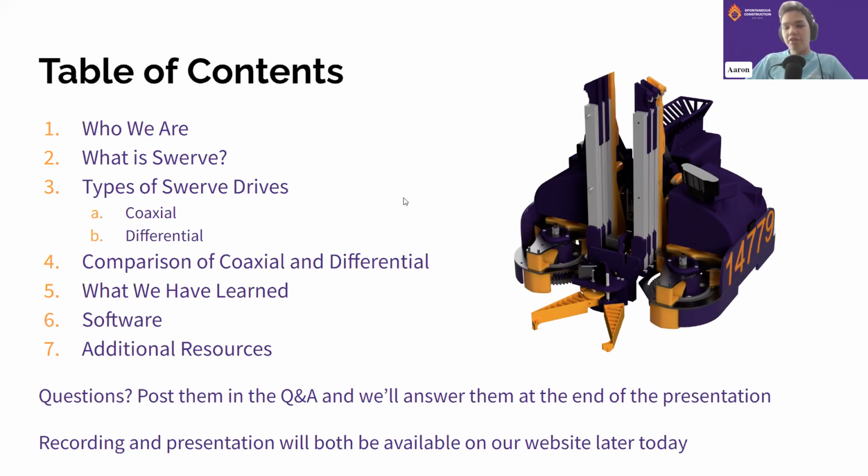This has worked fairly well for us, but I would recommend looking into other options for acceleration curves, because the moving average filter works, but it isn't perfect. There are some limitations, like you can't use it in the first few updates in a match, and using it for auto has been difficult to implement. So especially for autonomous, I'd recommend looking into trapezoidal acceleration curves, which you can actually view on Control FEC as well.